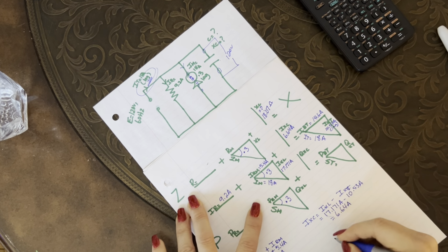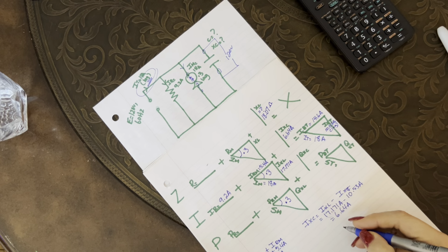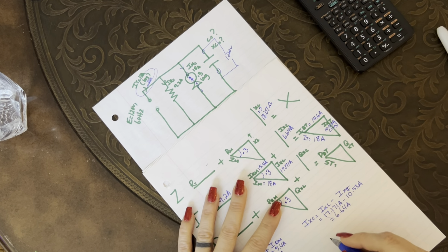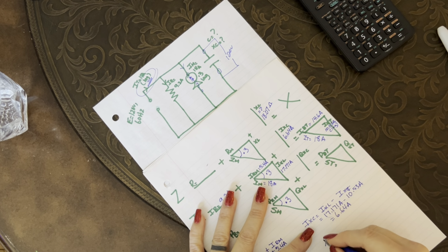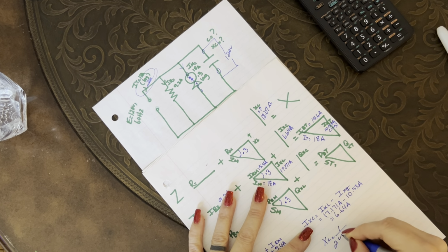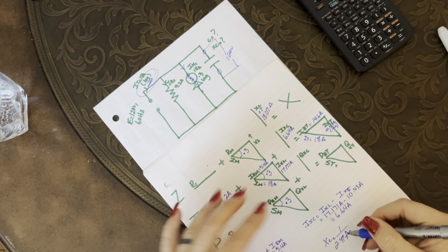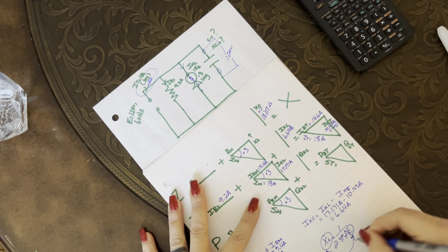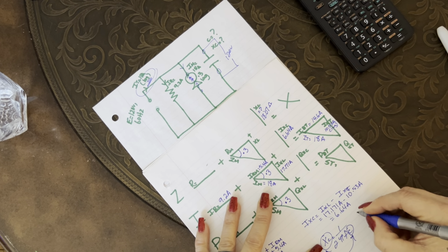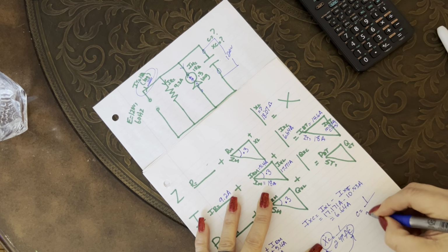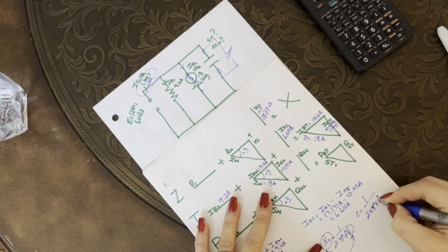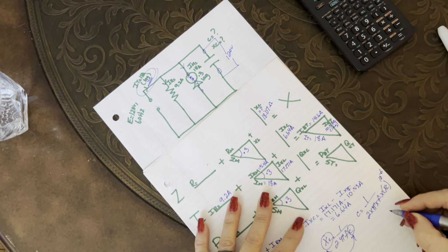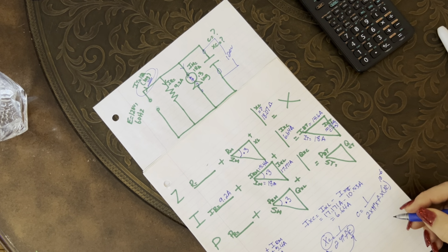The question wants my capacitance, right? So they want to know the microfarad rating of that capacitor. I've solved for my capacitive reactance. So we need to transpose the XC formula. XC equals 1 all over 2 pi FC. So whenever you have to exchange C and XC, all you have to do is swap them out. So in essence, our new formula is going to be C equals 1 all over 2 times pi times frequency times XC. And don't forget the 10 to the negative 6 because we're dealing with the unit of measurement for micro, right?